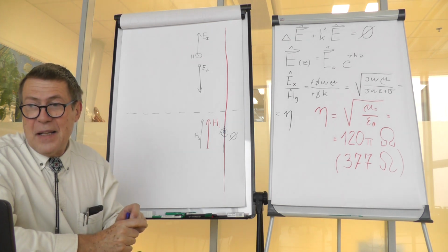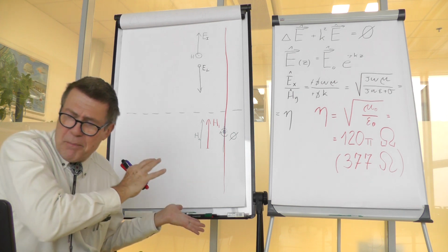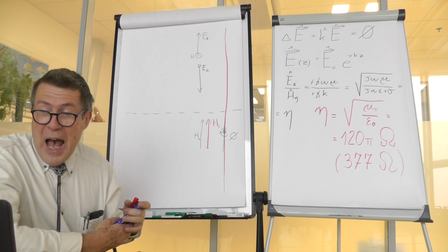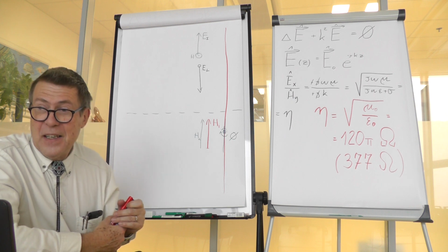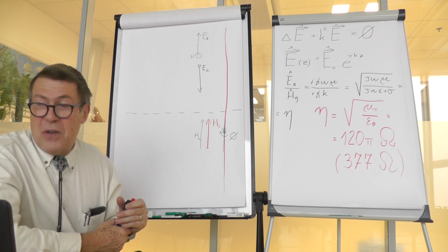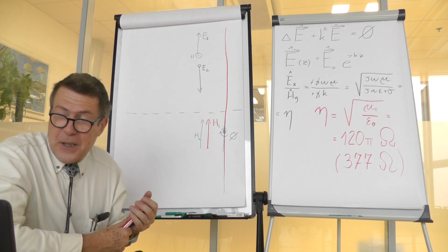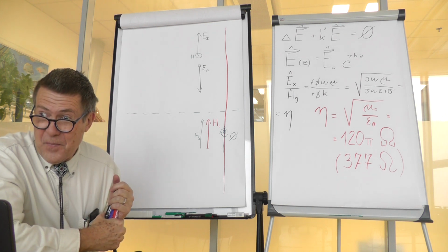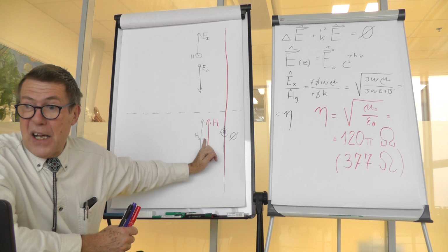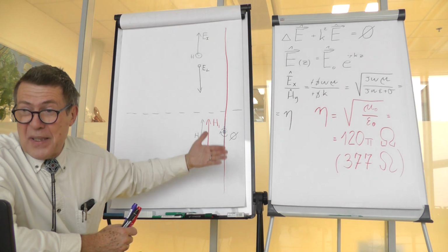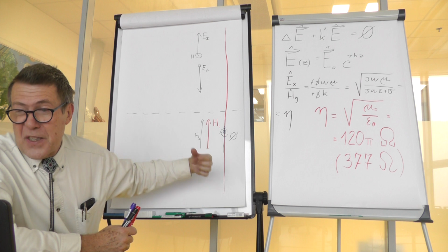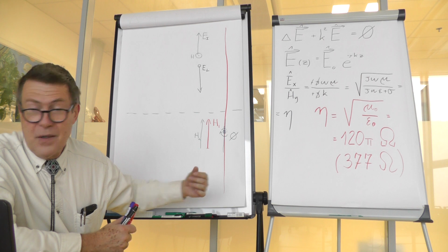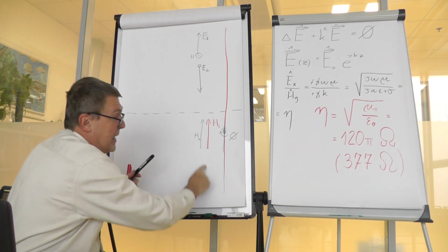But once there is a limited and very big conductivity, you cannot have infinite current density, because with an infinite current density and finite conductivity you would have an infinite power dissipation. And so what happens is, in a real case of a conductor, at the surface you have some layer of current, which, let's take a magnifying glass.